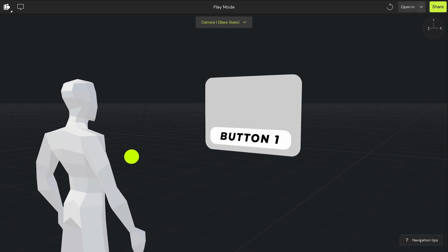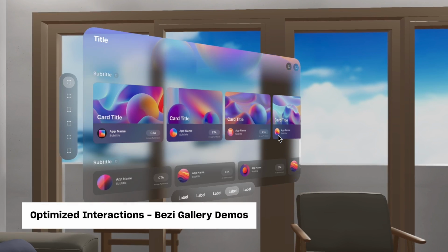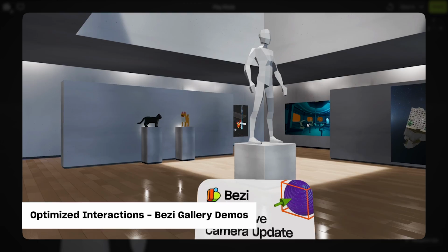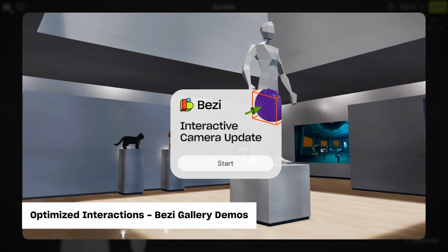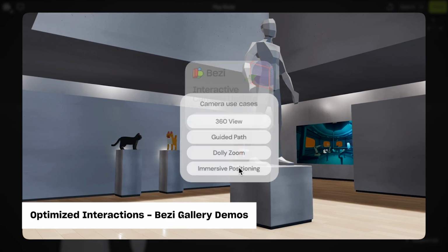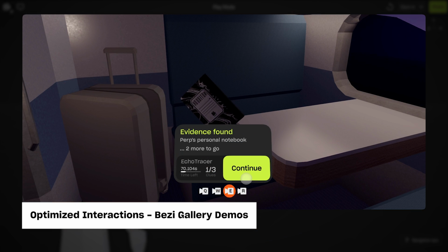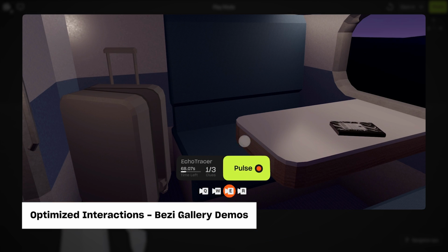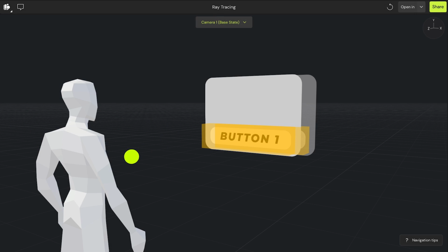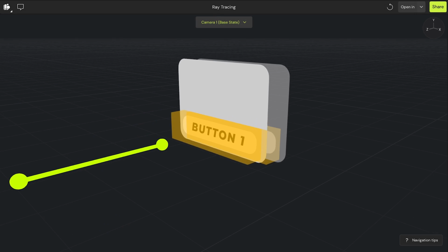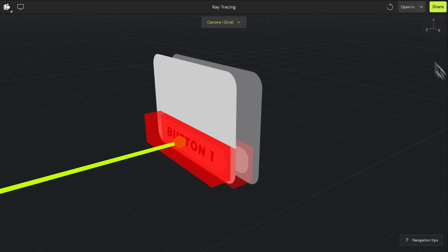When designing interactive prototypes in 3D, it's always best to approach it with a troubleshooting mindset. Here are a few things to keep in mind when composing your projects. Overlapping interactions may cause conflicts with one another. For example, when a screen transitions to another screen. This is usually done by hiding one screen by turning its opacity to 0. Often, the hidden button overlaps the other. Using this example that we built in Bezi, although it's not visible, the interaction is still there.